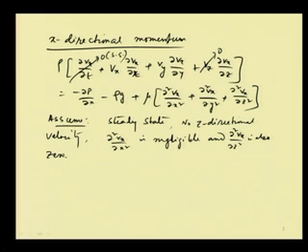So, then what is happening? Vx is not changing along the z direction. So what is happening is Vx is only changing along the y direction. Change of Vx along the z direction is not there. Change of Vx along the x direction could be there, but the gradient, that means del Vx by del x, is taken to be negligible.